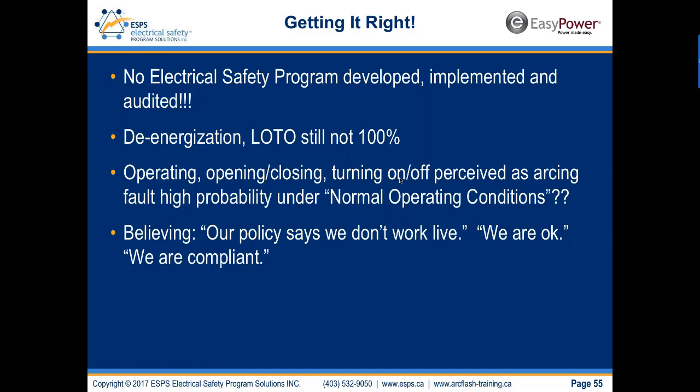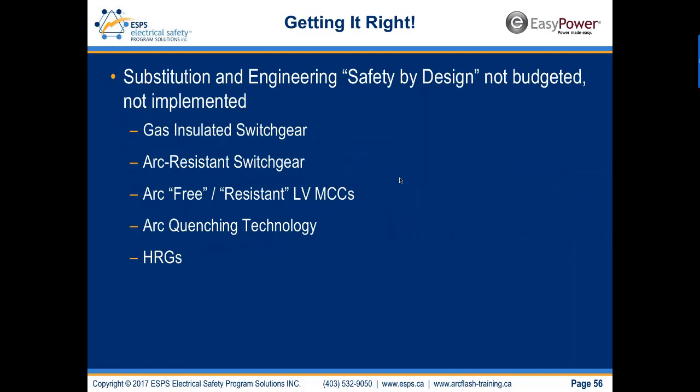Every electrician owns a digital multimeter and does voltage and current measurements, and those are energized electrical work tasks. So we've got to manage some of these perceptions, this misunderstanding, this misinformation. What I am seeing that's really good is gas-insulated switchgear being applied, arc-resistant switchgear, arc-free MCC designs, arc-quenching technologies, and high-resistance groundings all being considered as substitution or engineering safety by design solutions. So again, good things, bad things.